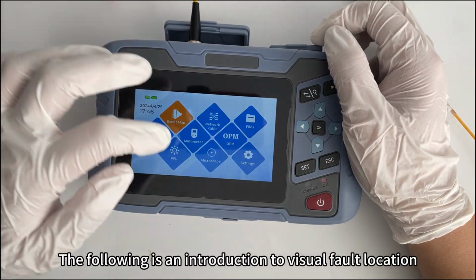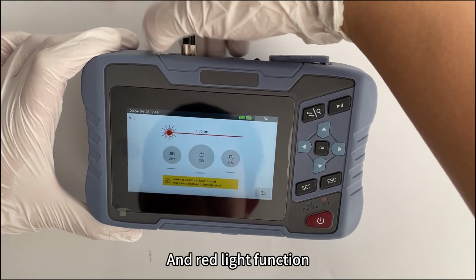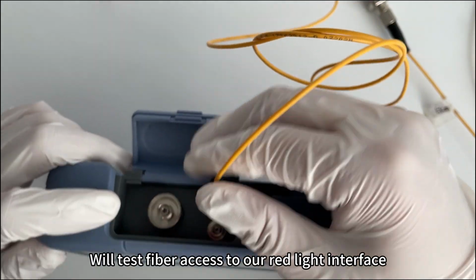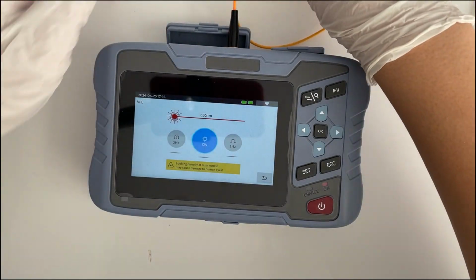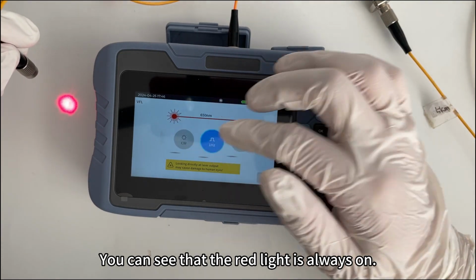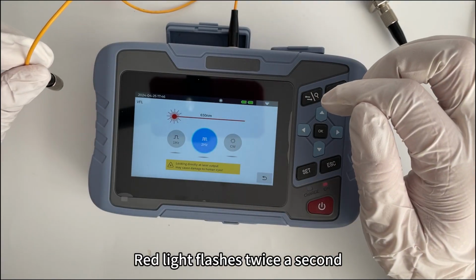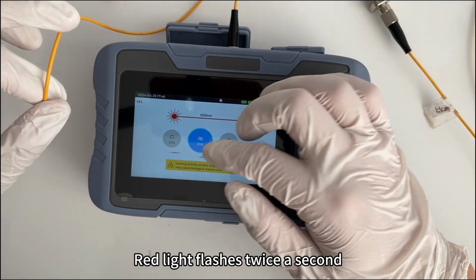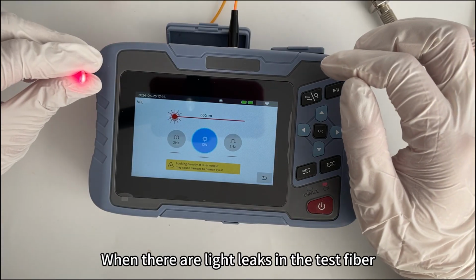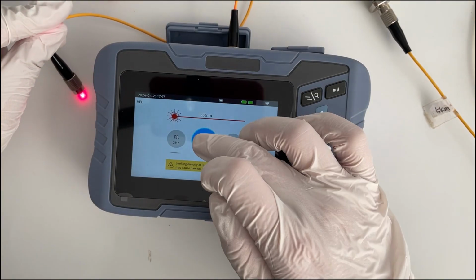The following is an introduction to visual fault location and the red light function. We'll connect the test fiber to our red light interface. You can see that the red light is always on. The red light flashes once a second. The red light flashes twice a second. When there are light leaks in the test fiber, you can see the light leakage point.